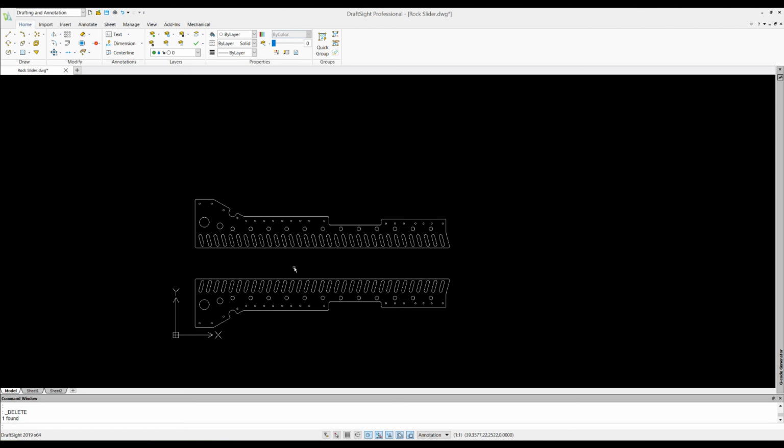If you're cutting it out on plasma, I probably would actually mirror it. But since we're going to cut it out on laser, it'll be fine. It'll look the same from both ways. With plasma, you have kerf and everything, and you always want to put parts on with the cut side towards the outside, the side that you see. When it comes to things like building a bumper, you don't want to put it in inside out, because all the corners look kind of funny, and they don't cut out perfectly straight. With laser, you can't really tell one way from the other. But since we already did it, let's just leave it.